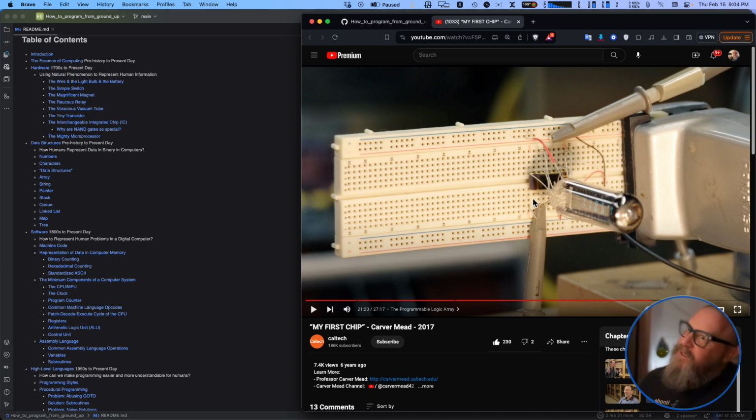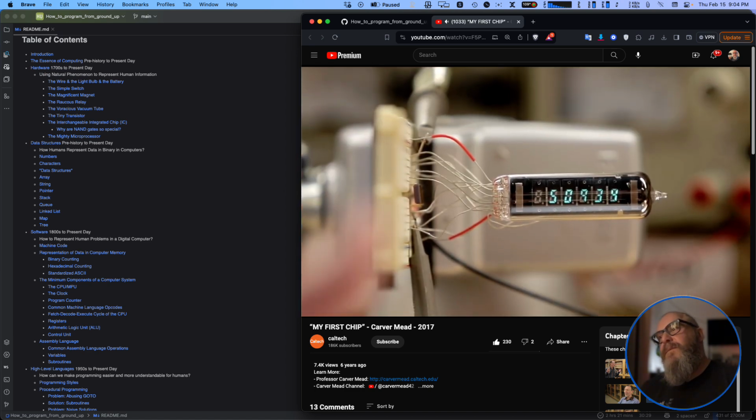So you can see he's just got one chip. He's got power supply to the chip, and he's got power supply to the display, and the power supply to the display may be different. But he's probably just got 5 volts on the chip, 5 volts to ground, and that's enough to drive these pseudo LEDs. There are little pieces of metal underneath that connect the wires together. Each of the little wires from the tube is hooked up to the appropriate pin on the chip.